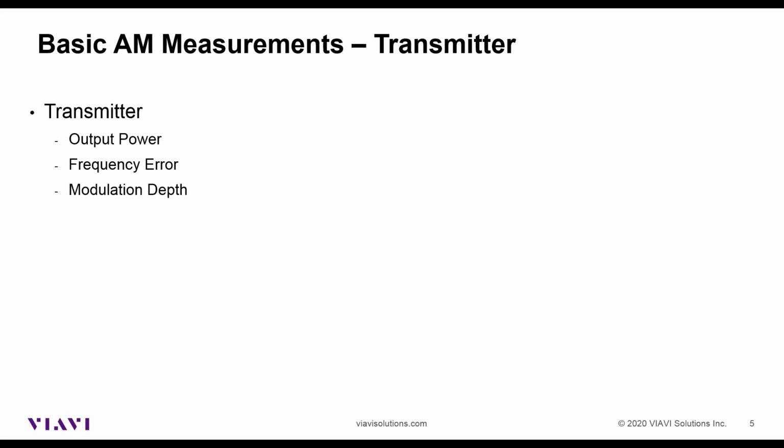Obviously, if the radio is too far off frequency, then the receiving radio may not be able to pick up the signal. We'll look at the modulation depth. So what percentage modulation do we have, and is it correct? We'll look at the distortion, so the audio signal that we recover. We want to look at the quality of that audio signal.